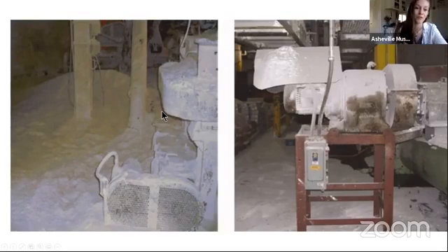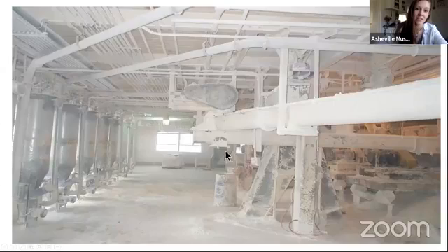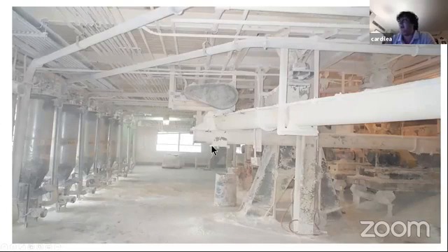So if you lit a match in that room, would it just explode? This one right here? Yeah. The problem is you probably would have a minor explosion to start. And then what will probably happen is, see all this stuff. This is where you usually see a loss happen. That's a really good question. If you put the dust in this room, you probably would have a flash. And then there would be a bit of a shock. And then all the sugar from these upper areas would come down into the air, create an even larger environment for there to have an explosion. And then that secondary explosion probably would be what would damage this room. So yes, if you lit a match and you had a big enough ignition source, you could have an explosion occur in this room.